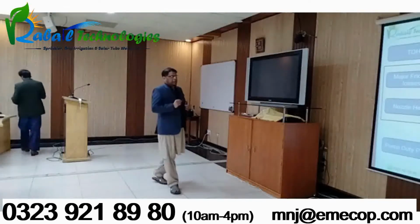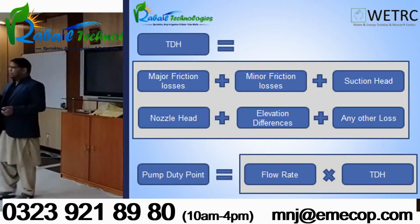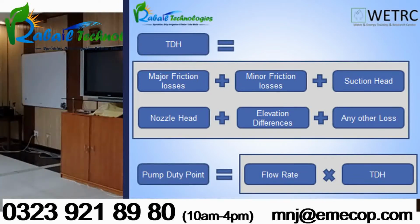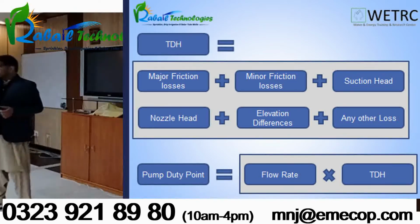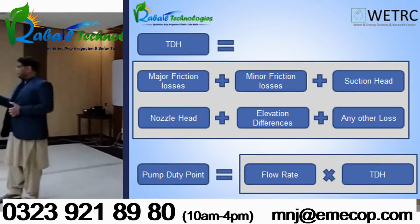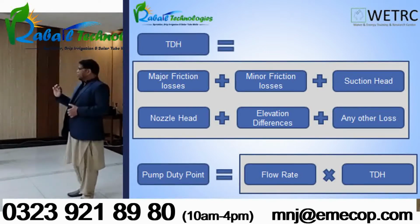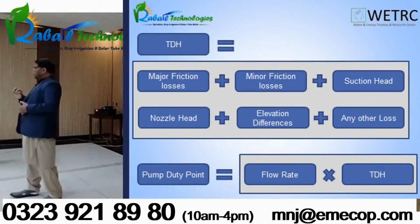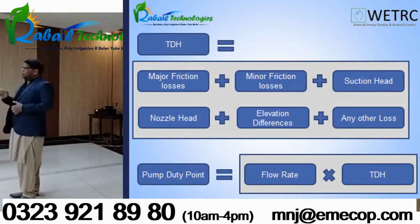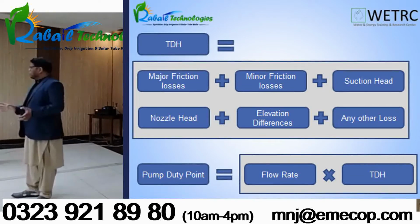So TDH is total dynamic head. Contrary to the TDH, the term is total static head. Total static head is the one where there is no flow. When there is no flow, we call it total static head. And when there is a flow, it's called total dynamic head, and the difference between the two is the friction losses. Because if there is no flow, there is no friction loss.